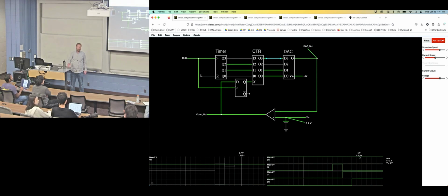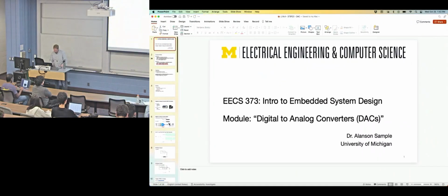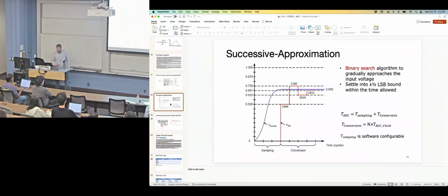Yes? The sampling time is the time, the sampling. Is the time to let the signal go to 0 to the analog value? Yeah, the sampling time, it doesn't always happen at 0. It's the time it takes to take the value in. You're talking about this value here, yeah? So you're not always coming from 0. There's no guarantee of that, but it's probably the worst case time to go from some value to something that's stable, to charge up that capacitor and then hold it.